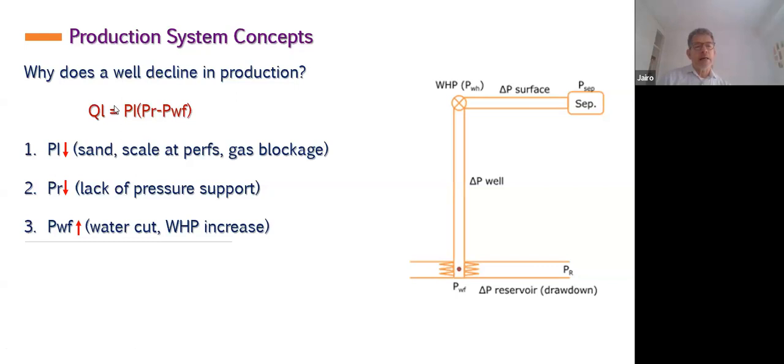PR will decline because of lack of pressure support, so we don't have an active water support or gas support from the gas cap or whatever.